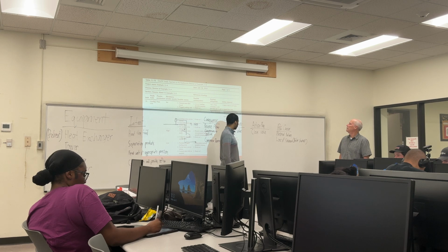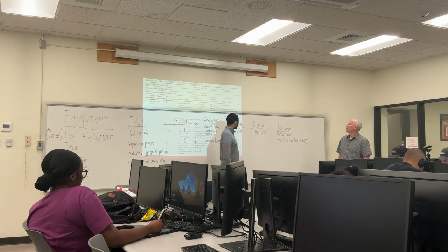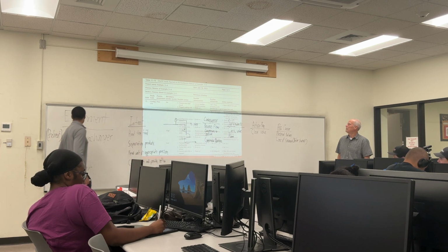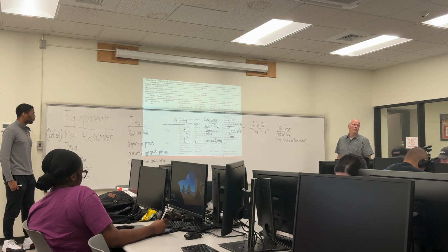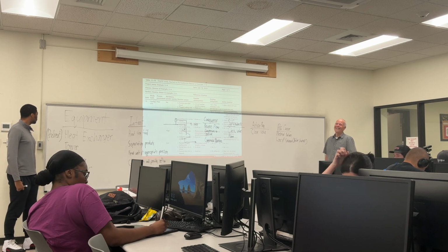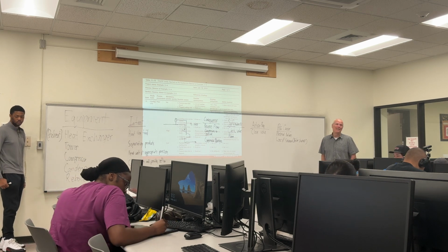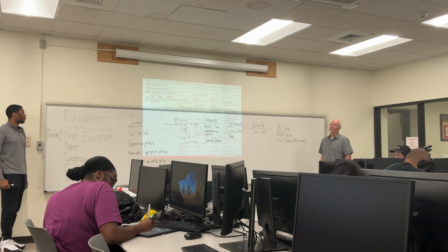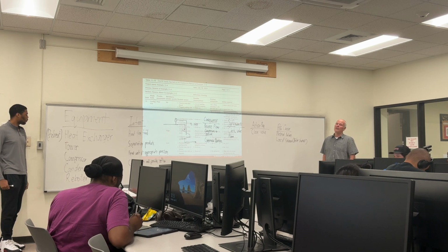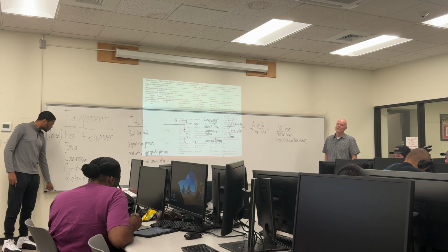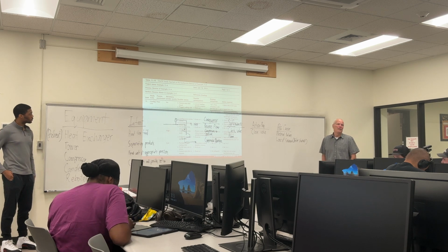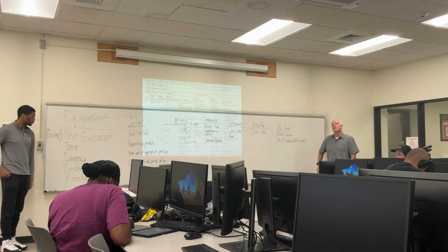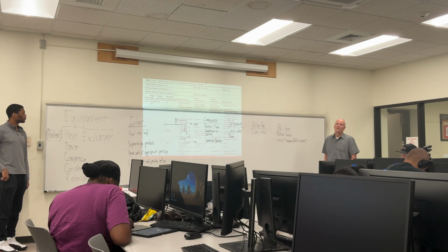And let's see. Oh, we pretty much covered this. Is this a big hazard or not? Is destroying your compressor a big hazard? Could be. Most compressors are really expensive. Any part replacement is a long lead time. You're shut down for a long time, and believe me, that is very, very expensive. So yeah, it's a big deal. And plus, if the compressor breaks spectacularly enough, you could lose containment.